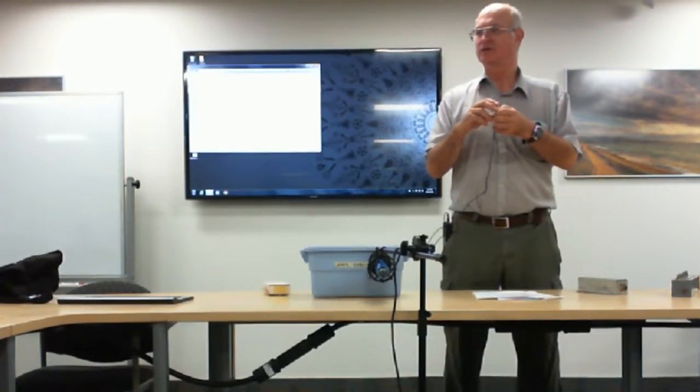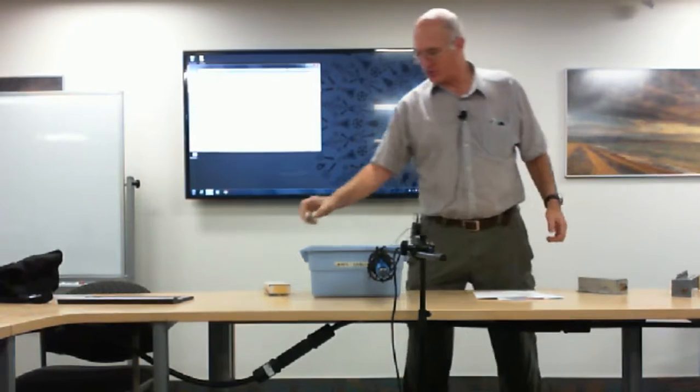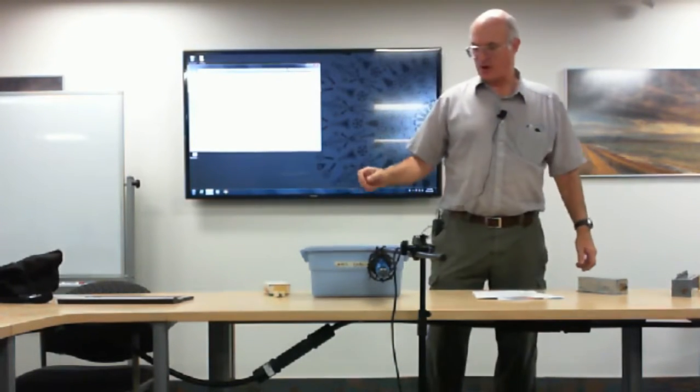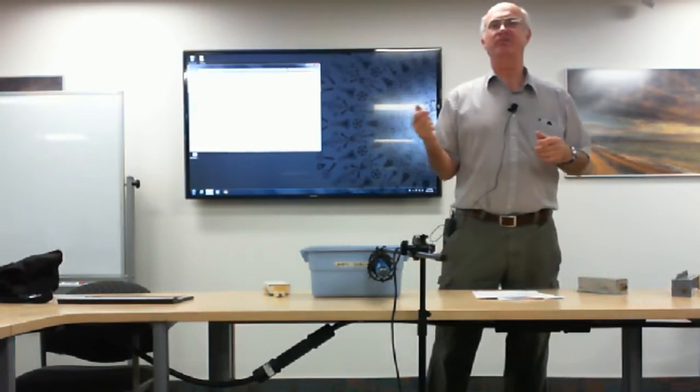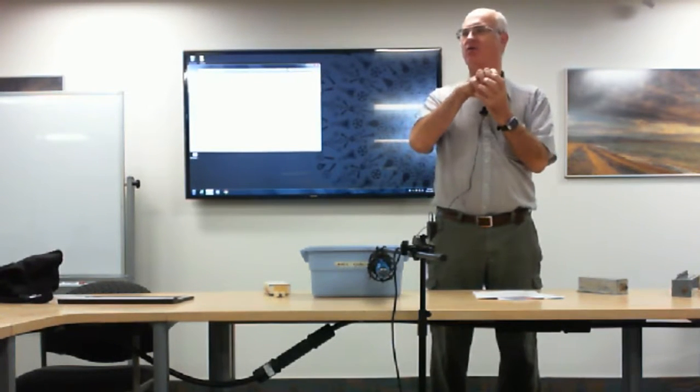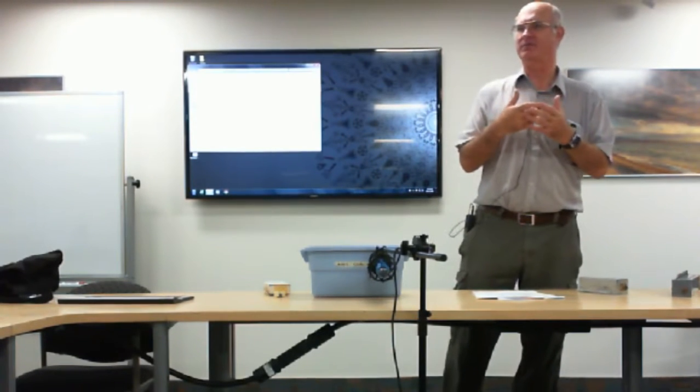Isn't that called a balun? No, this would be like a balun, but it's not a balun. It looks similar to it. That's another thing. Just a toroid alone, and here's why. If you have current going through a wire, and you place a ferrite core around it, what's going to happen? That current is going to induce another current inside the ferrite, right? Do you remember that from transformers?